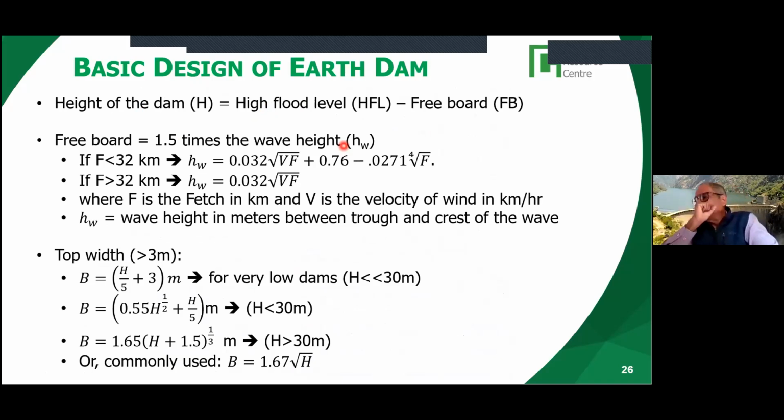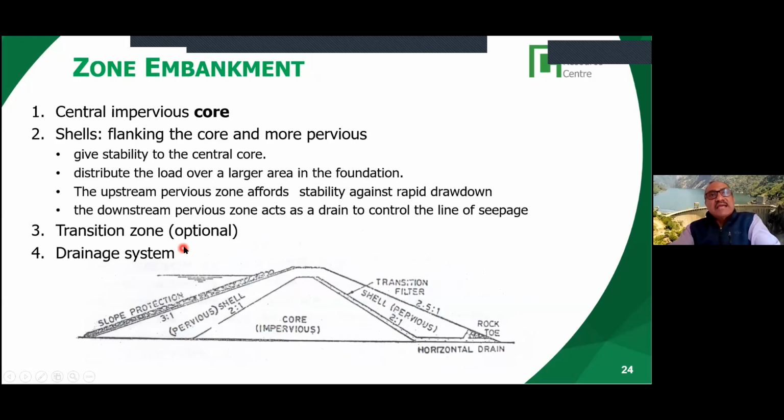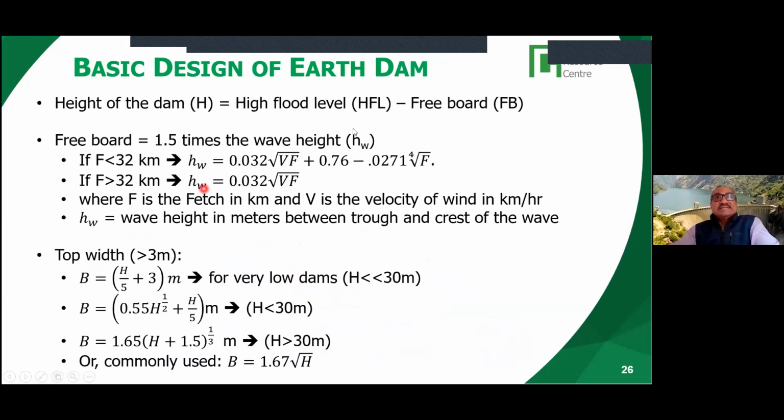So the main design is the height of the dam. You have to decide what the height of the dam should be. To decide that, you should know the high water level. This high flood level is decided by a hydrological study.